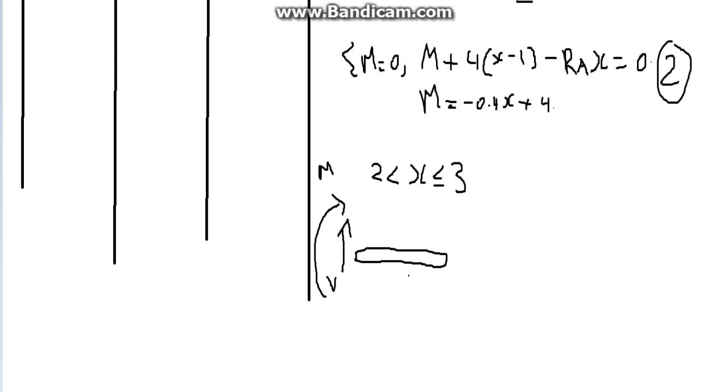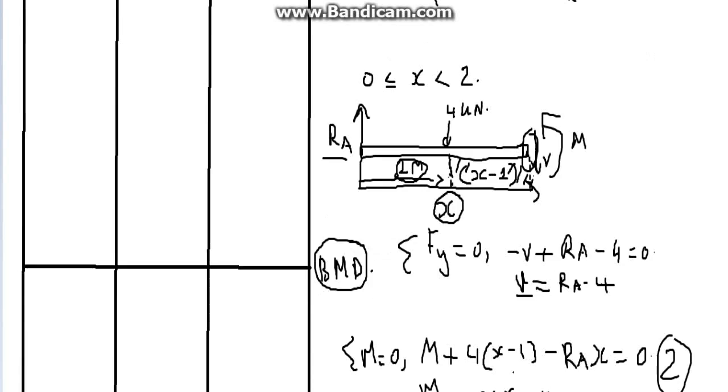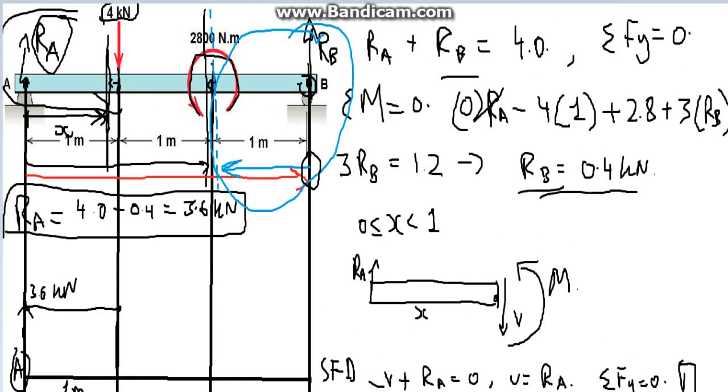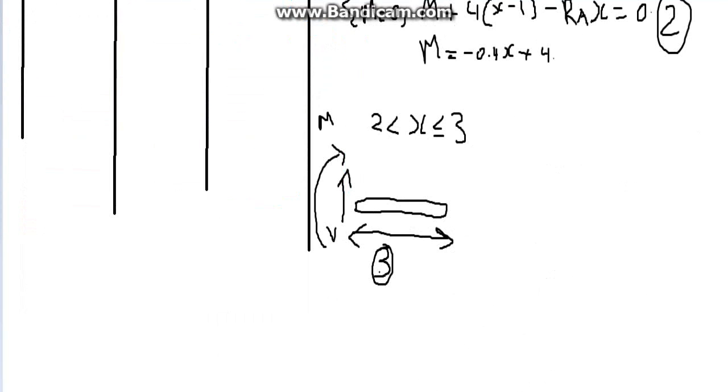There we go. That is the first hard part done. Now the second hard part is actually knowing what this distance here is. Now here's a general thing that you must keep in mind. Overall distance of beam, 3, because we're working from the overall distance to this point defined right before here. 3, which is the overall distance, subtracts the x, the unknown distance that we want as a variable for our formula.